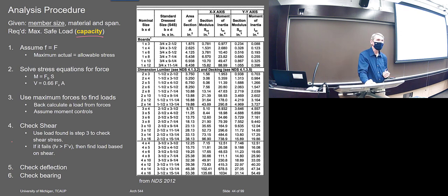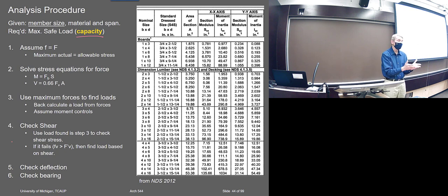I was going to say, would you ever go less than 12 inches on center? Or is that just less practical? Yeah, there's no code reason that you could not. You could, but it's a matter of economy, I guess. If you're going that close on center, you probably could do better just to get a deeper beam, because you've got to think of the other expenses. First off, you've got to buy that many members, and that's probably more expensive than just getting a slightly deeper member and spreading it out.